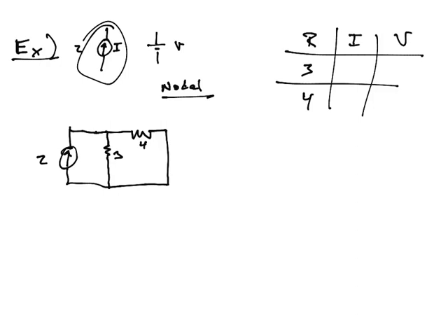There's a few things to remember when you do nodal analysis. First thing you're going to have to do is choose a spot on your circuit to be what's called the ground. And the ground symbolically looks like this. So it's almost like a voltage source, but it's got 3 little lines instead of 2. And where you place this symbol is going to determine this point of my circuit is defined to be 0 voltage. That's the ground. 0 voltage is there.